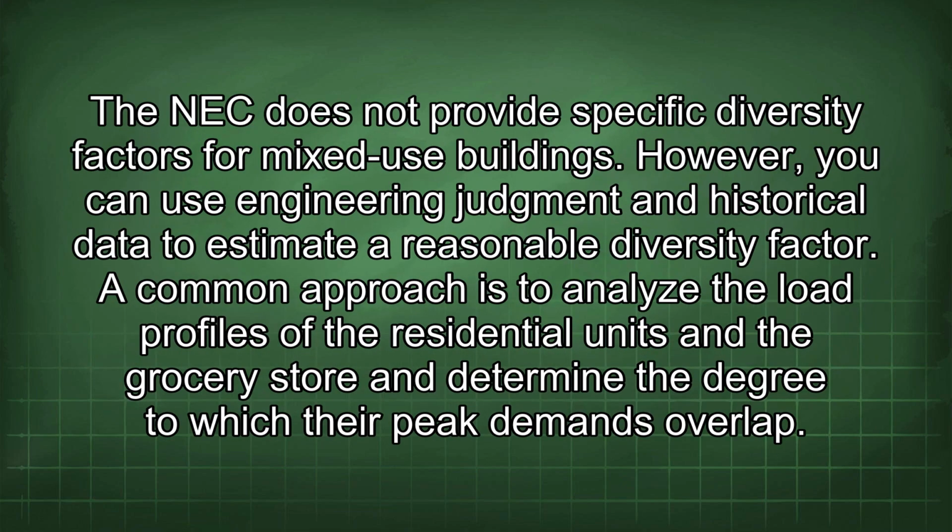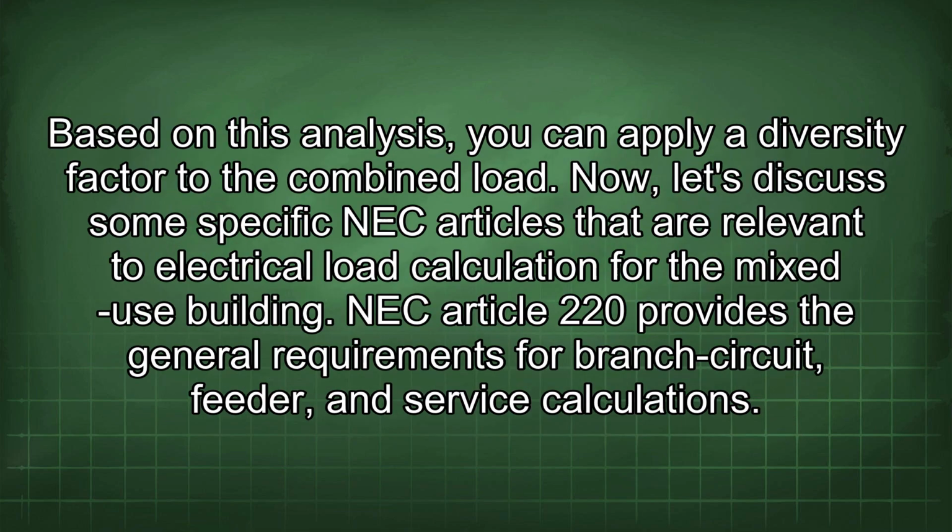The NEC does not provide specific diversity factors for mixed-use buildings. However, you can use engineering judgment and historical data to estimate a reasonable diversity factor. A common approach is to analyze the load profiles of the residential units and the grocery store and determine the degree to which their peak demands overlap. Based on this analysis, you can apply a diversity factor to the combined load. Now let's discuss some specific NEC articles that are relevant to electrical load calculation for the mixed-use building.